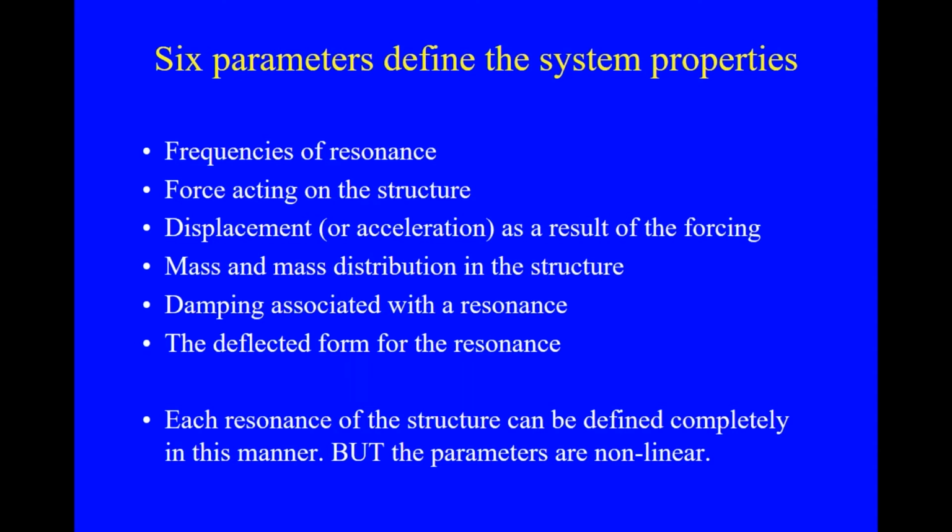We've got a modal stiffness, and we've got the modal forces. Modal, that means that we are dealing with a single resonance at a time. These equations apply to a whole series of resonances of a structure, and we can manipulate them and get more common parameters like the frequency, the inverse of the period.